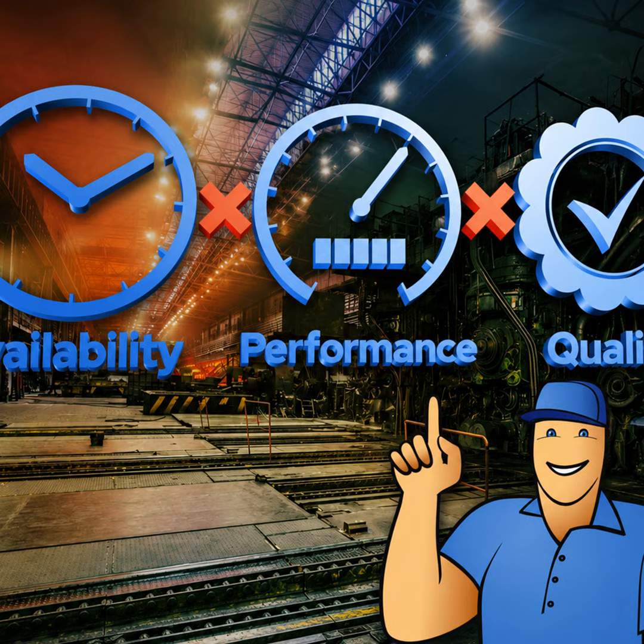Availability calculation. During the shift, you had several interruptions. The setup at the start of the shift took 45 minutes. Then there was an unplanned breakdown, maybe a motor issue, which stopped production for another 30 minutes. Minor adjustments throughout the shift also resulted in 6 stops of 5 minutes each, adding another 30 minutes of downtime. Altogether, those interruptions added up to 105 minutes of downtime.